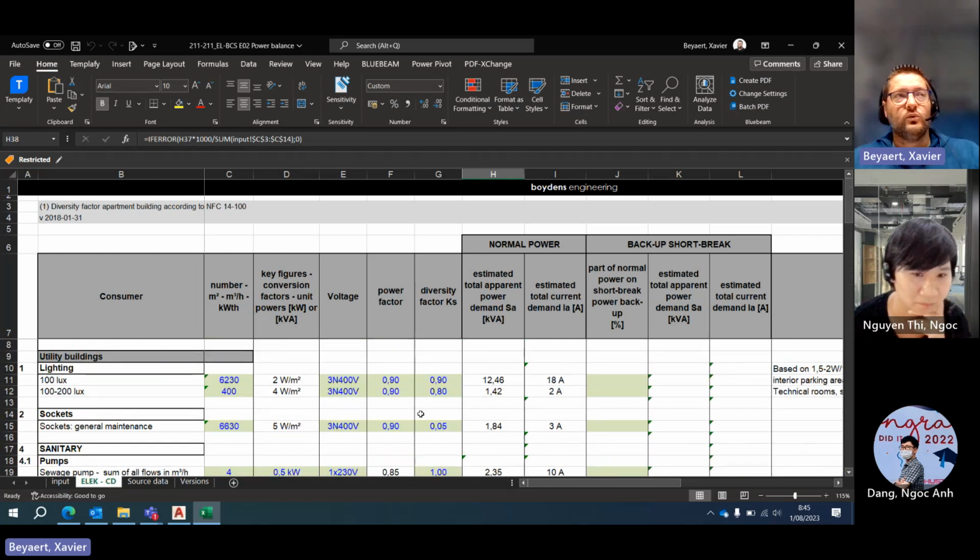But be aware to have selectivity on the protection units, so that the protection unit first in your circuit will shut off and your first one not. That's selectivity. If you want to reach that, you have a minimum current of 63 amps. So we will never have an electrical panel that's lower than 63 amps, a main electrical panel, just for the selectivity.